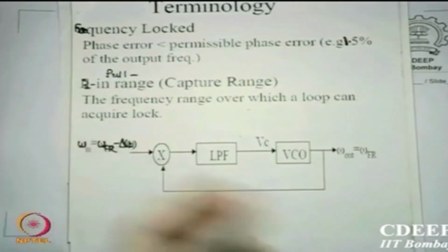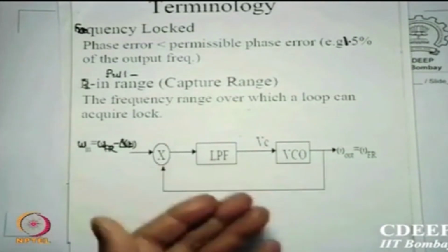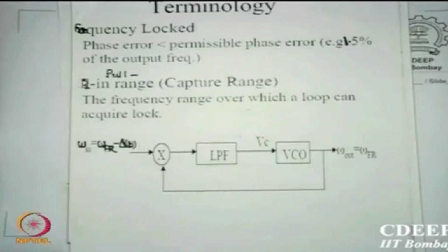Ideally it should be 0, it should lock exactly at that frequency. But it may not, because components can never give 100% lock. So a little drift always remains, but that should be permissible for you. People also give slightly different statements about jitter.